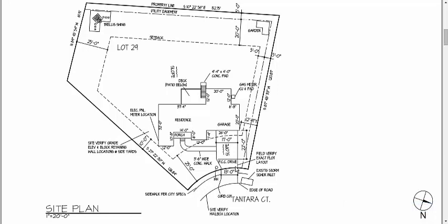In this case, you see that arc right here. And then if we extend that black line back, you see how that comes back to this point up here. That's your back lot pin. A lot pin is a location of this point right there. You'd have another lot pin right here, here, and here. Now those lot pins are set by an engineer, typically a civil engineer, that hires a surveyor, or maybe it's their own company, to come out and locate each of those corners. Again, that's your lot pins, so you know exactly where your property starts and stops.